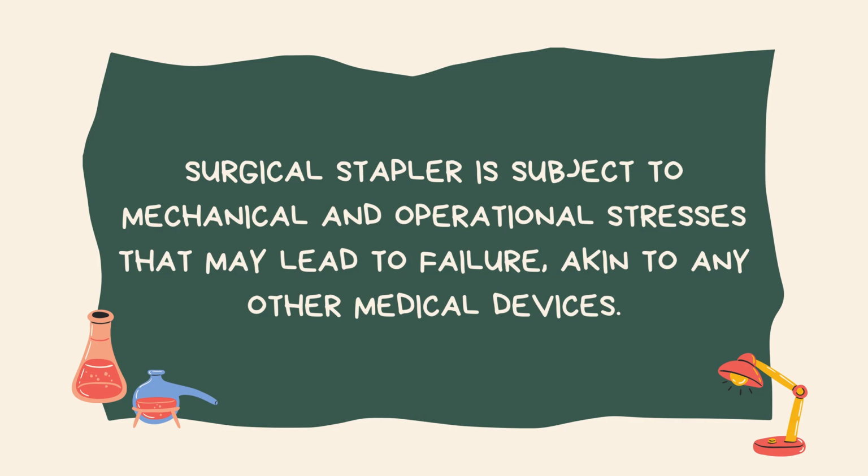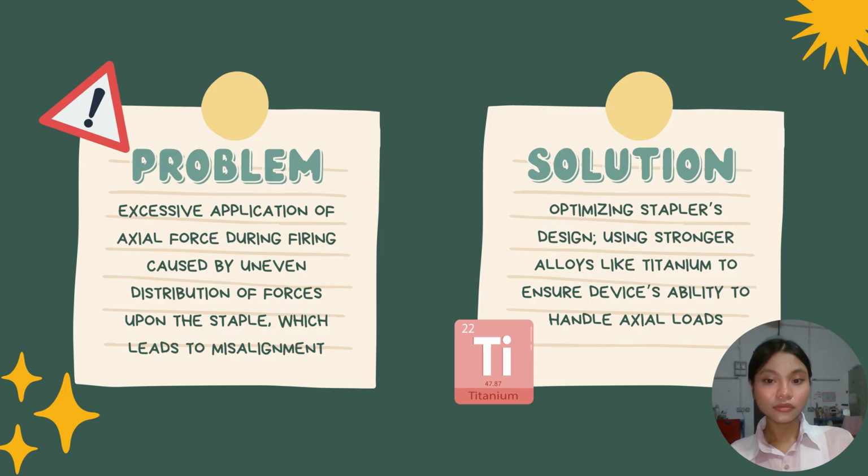Surgical staplers are subject to mechanical and operational stresses that may lead to failure, akin to any other medical devices. One of the problems is excessive application of axial force during firing, caused by uneven distribution of forces upon the staple, which leads to misalignment. To solve this problem, we can optimize the stapler's design by using stronger alloys like titanium to ensure the device's ability to handle axial loads.